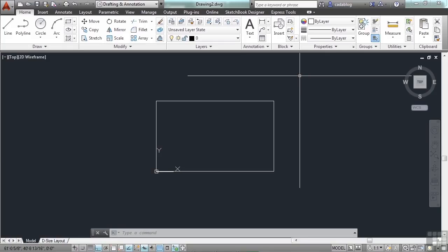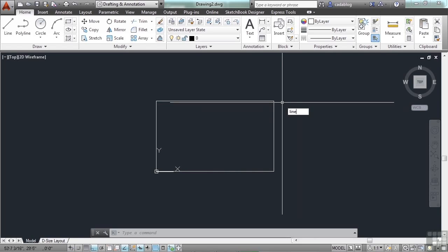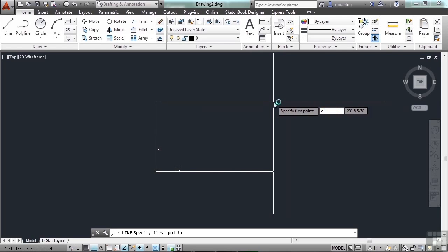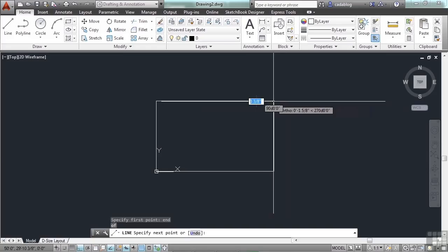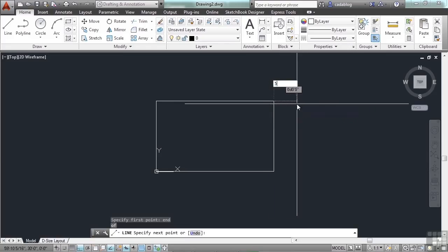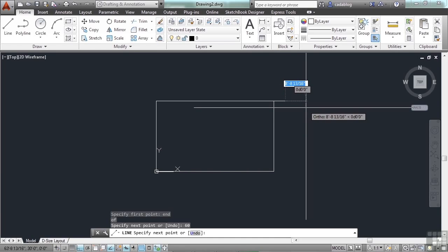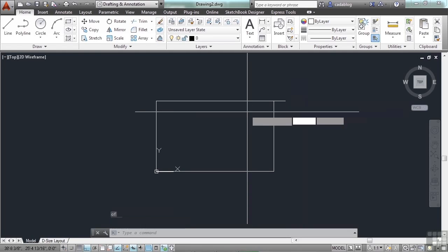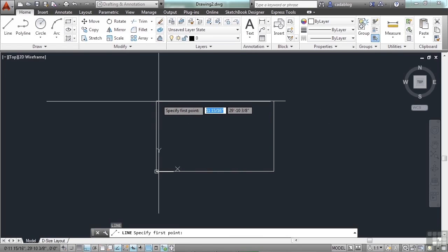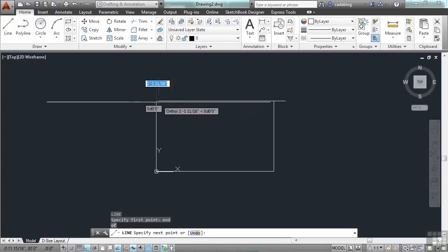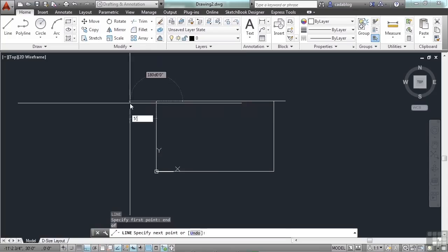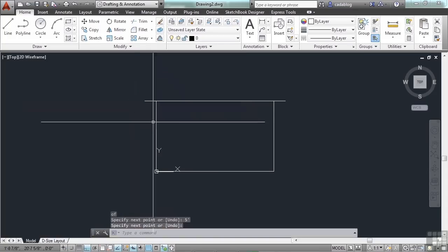Now let's put in a roof. Let's go to the top right corner. Over here. Start the line command again. Go to this endpoint. Press E and D. Enter. Pick that line. And now let's go to the right 5 feet. Or you can type in 60 inches, which is the same thing. And that gives us our 5-foot line. Now let's go to the other side and do the same thing. Start the line command, type in end, grab the endpoint, go to the left 5 feet, enter. Press enter again, and here we go.